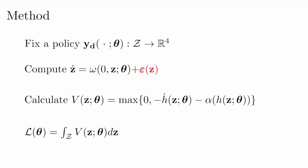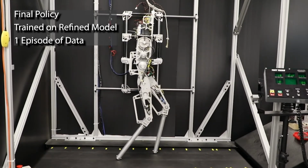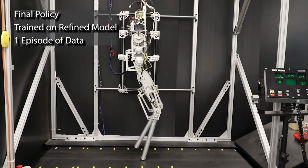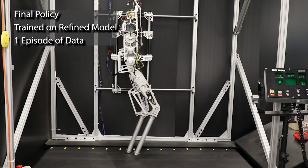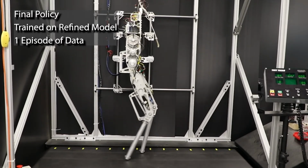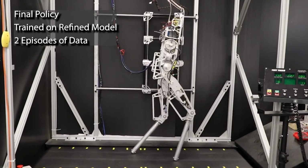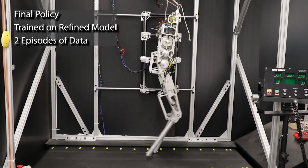We refine our previous policy by training on the zero dynamics augmented with the learned residual. After one iteration of learning with the hardware data, the following policy is realized. Notice the stable walking, but oscillatory output tracking on the legs. This process is repeated once more, and aggressive, stable walking is generated.